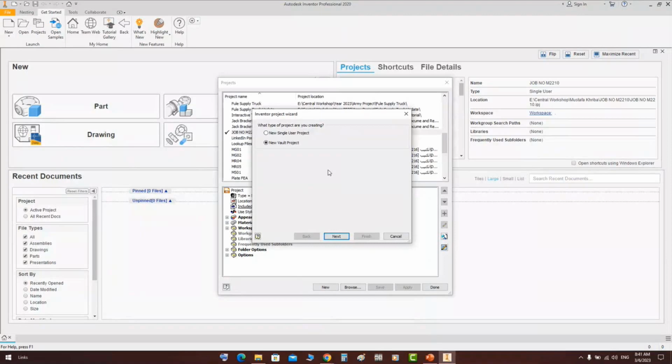So you should have a Vault application to make this project and to give the team permissions. So, for example, the one who will make the pressure vessel will not be able to edit the piping, and if you reverse it, the piping one will not be able to change the equipment or steel.